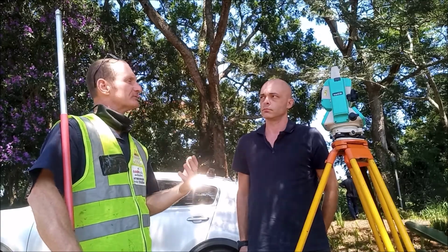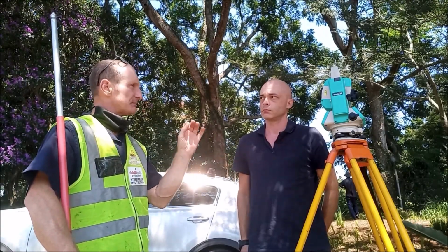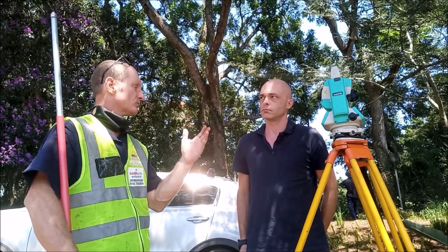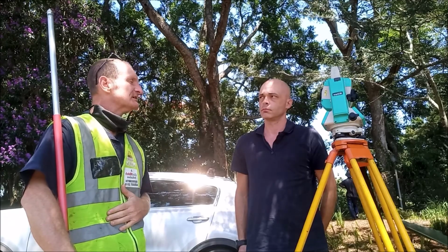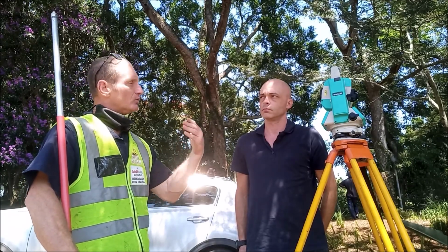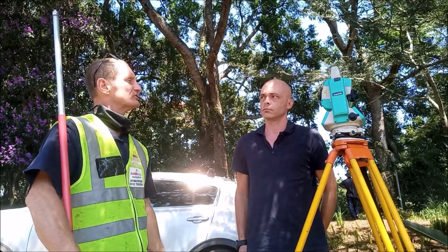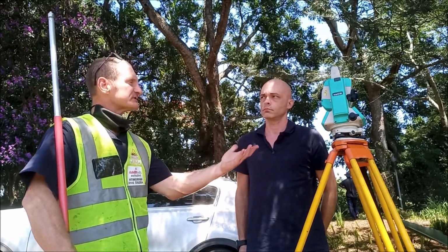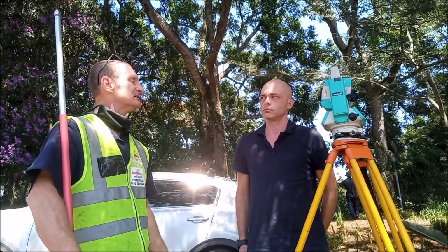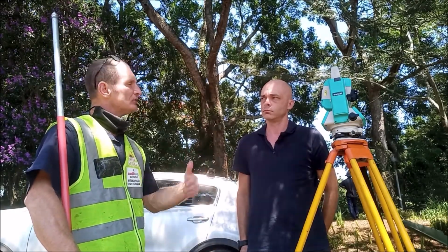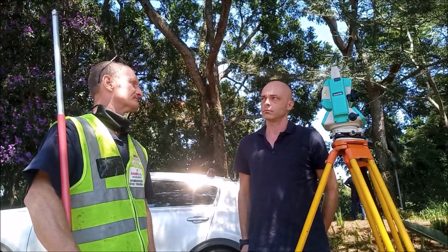So we have to have a certificate for the device to say that it is within a specified parameter of tolerance, whatever that may be, 0.1 of a millimeter or 1 millimeter. Generally we would have this calibrated once a year, and it is held once a year as a certificate. If for some reason we drop the device or damage it, or suspect that it may be out of calibration, we may even send it in on an extra occasion to have it calibrated.